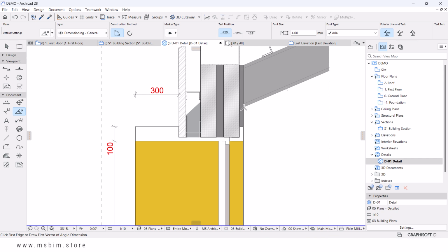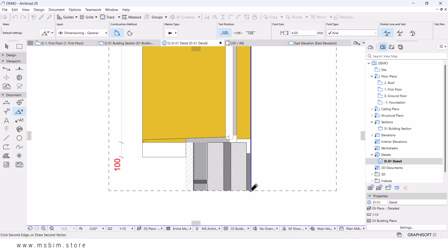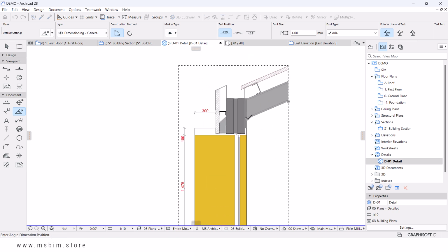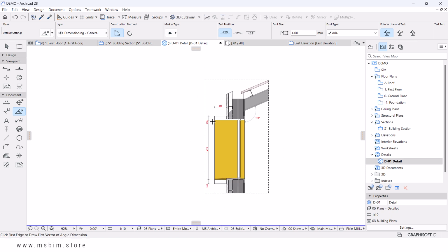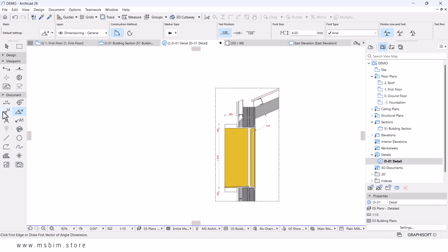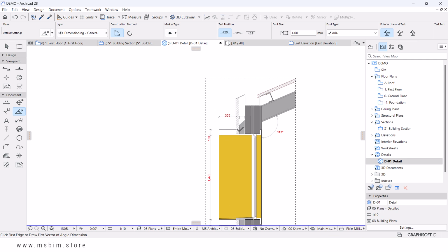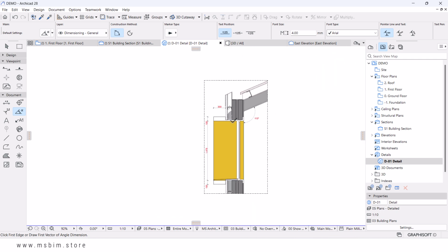You have to first specify the anchor point of your pitch, then I will select the 2 wings, then go back and click, then you can place it. Perfect. So yeah, basically this is pretty much what I'd want, and then I'll add more details like annotations as well, because on the section I couldn't place much of the annotation, especially for these elements, for the purlins and stuff like that. So basically I'll leave this exercise for you because we already covered it on our section.